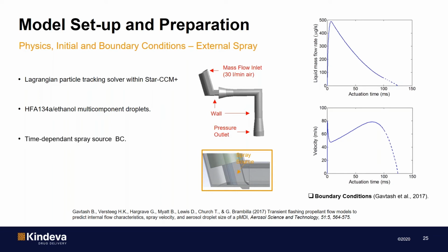The pMDI cloud basically undergoes rapid evaporation with strong heat, mass, and momentum transfer in the near-orifice region. To capture these strong interface phenomena, we use a two-way coupling algorithm in STAR-CCM+ to capture the effect of the particles on the surroundings.